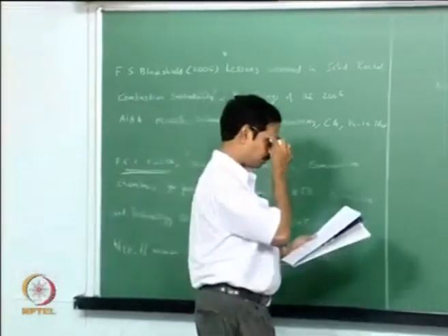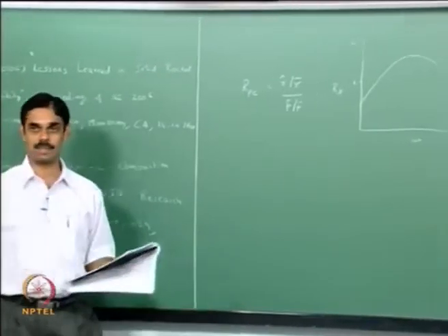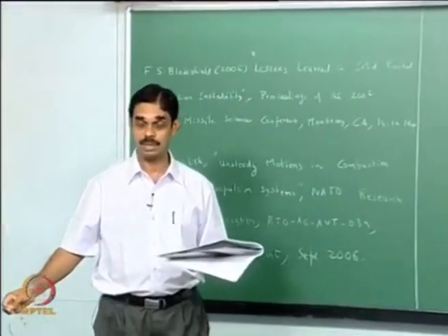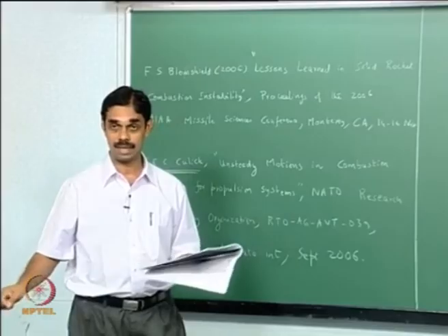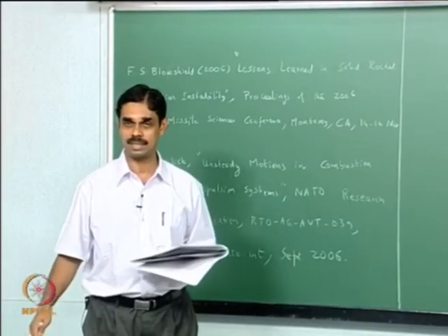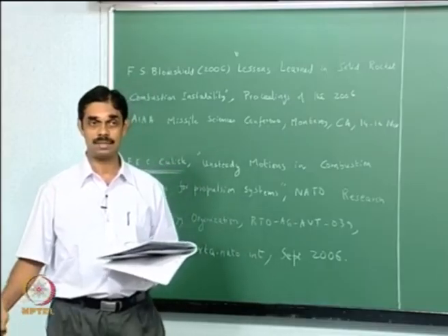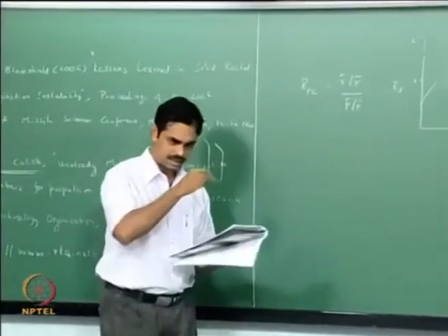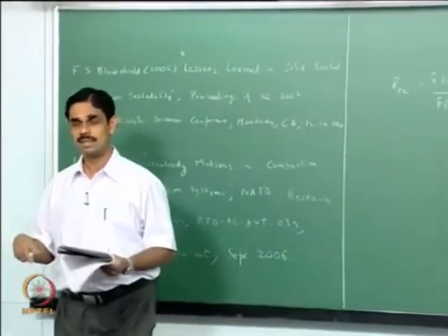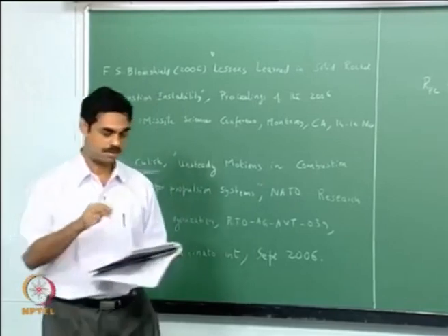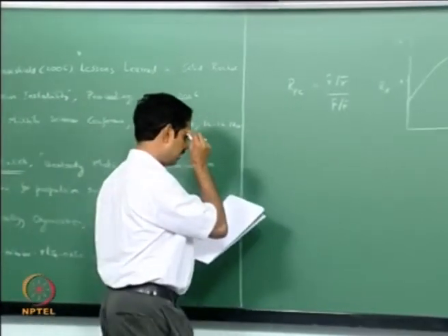Now we should measure the propellant response, as I mentioned, because that is the input to the stability program towards calculating alpha, and there is no way you can simply guess the propellant response. It is a function of various parameters, so it is really a non trivial task. There are many ways to measure the propellant response. I will tell you the most popular way, which is using a T burner.